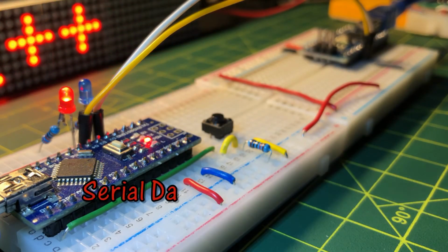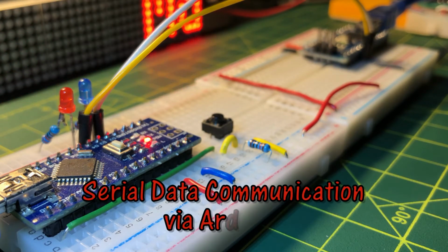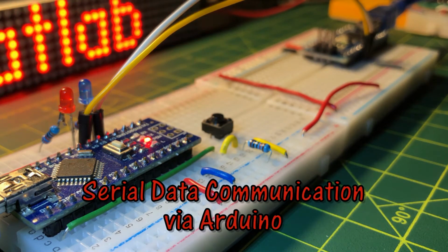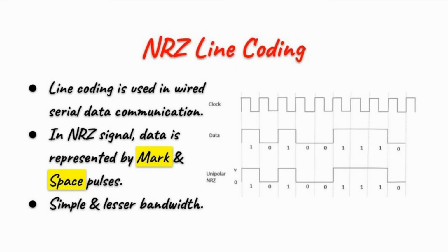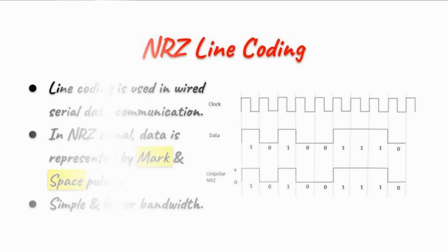This video demonstrates the fundamentals of wired serial data communication using Arduino. Wired serial communication uses line coding to transmit data from transmitter to receiver. One type of line coding is non-return to zero coding, NRZ coding.